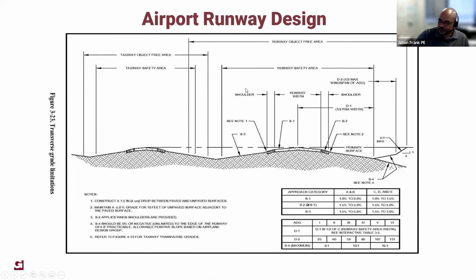This drawing also shows what I was just talking about earlier on some isometric drawings and in the chart, as it projects the runway safety area in this case. It's going to be anywhere from 250 feet from centerline, so 500 feet total width here, and this could be 800 feet wide here on the object-free area. Anything in here is really affixed by function, such as an edge light, a centerline light, or a threshold light. So it has to have a purpose in order to be within the area.